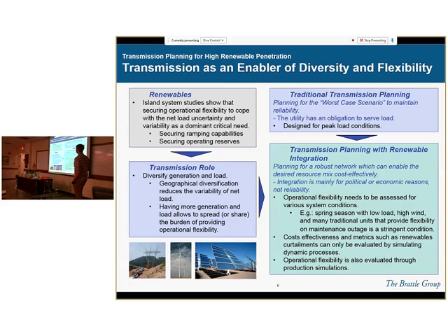And so these considerations, if they're critical aspects of integrating renewables, need to make their way into transmission planning. Now we have this coming together of traditional transmission planning, where we consider the worst-case scenario to meet reliability requirements, but we also consider the dynamics of the renewables, and how bringing transmission in with renewables can bring geographical diversity to reduce the variability in the wind, and also bring more flexibility by allowing us to exploit generation in more different locations of the system simultaneously.